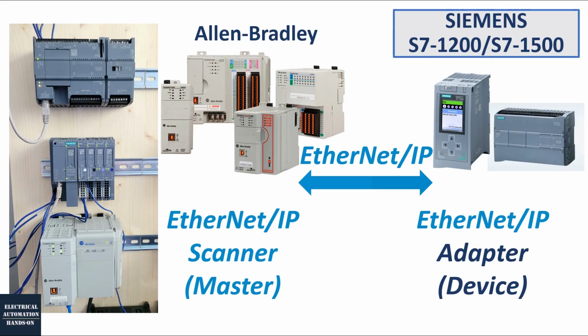Hello everyone, in this video I'm very glad and excited to introduce this new feature. That is how to implement the EtherNet IP adapter feature into Siemens S7-1200 or S7-1500 PLC. This feature will allow the Siemens controller to run as an EtherNet IP adapter, basically the device. So any other Ethernet IP master can communicate with the Siemens 1500 PLC or 1200 PLC.